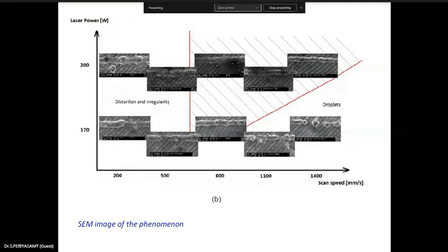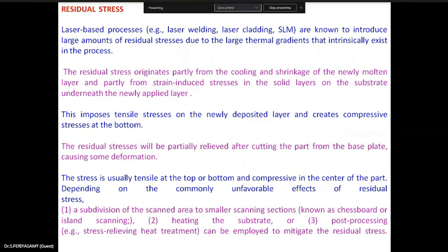While it rolls out, the water shape is like a sphere or somewhat a rolling element. 99% is a sphere. That's a ball, that's rolling. Same thing will happen here. The balling occurs when the molten material fails to wet the underlying substrate.